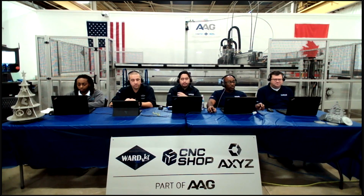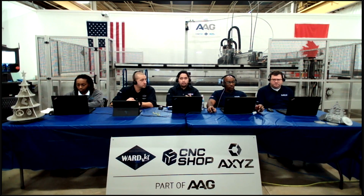But recently and over the years, we've looked at different options for oscillating knife devices. And we know that there's certain devices that are best suited for certain materials and applications. So a thick foam that's highly dense would benefit from our pneumatic cutting device that ranges at a specific number of oscillations per minute, whereas thinner paper material will definitely fare better with a slower or shorter stroke oscillating knife.